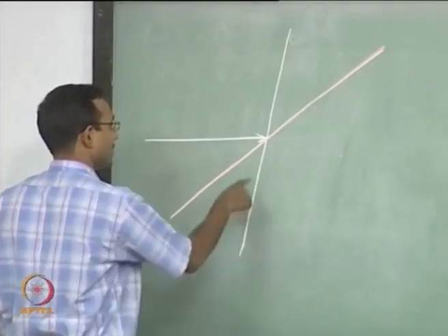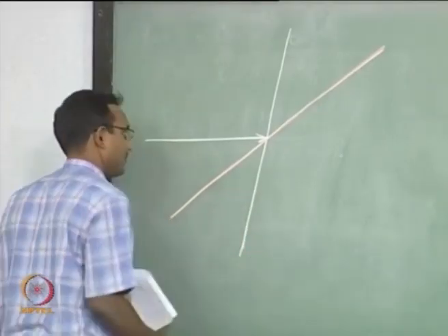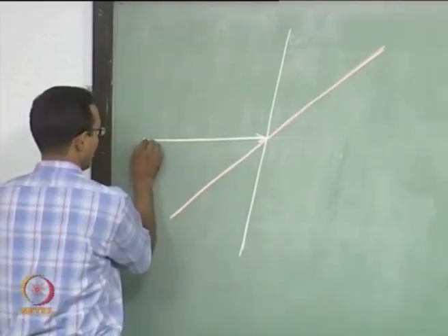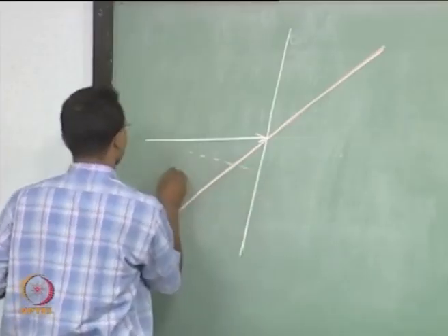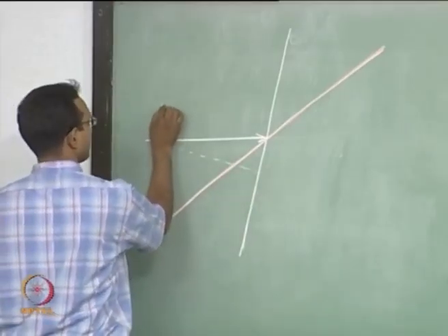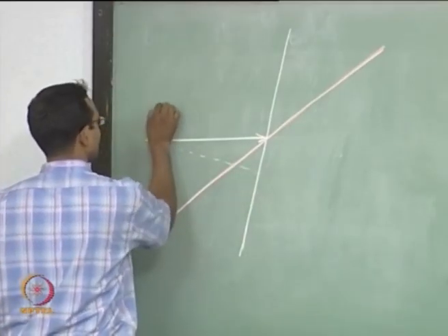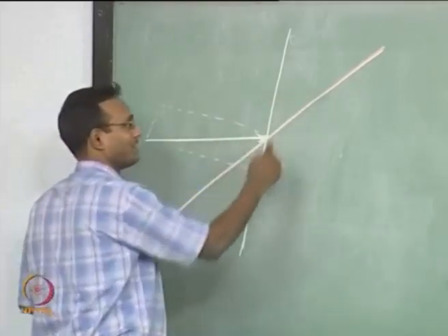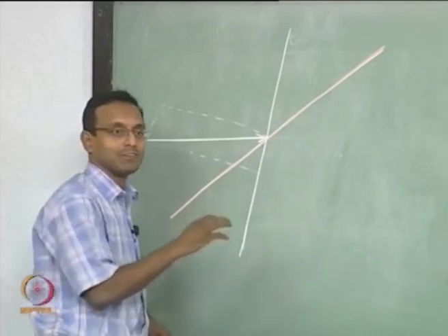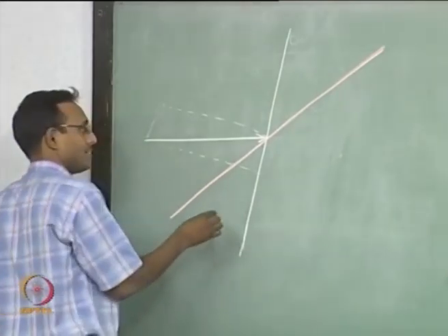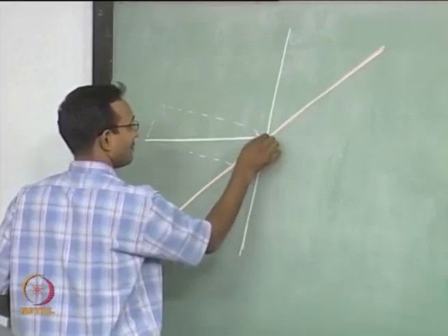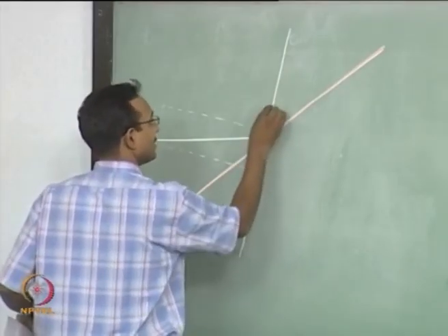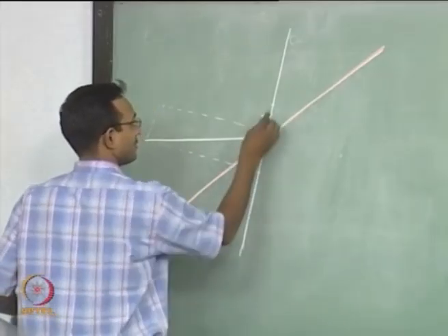So, let us look at only the strong solution first. I have to figure out the normal component. So, I have to drop a normal for this vector. I am drawing in a particular way so that it looks like the downstream velocity vector can be drawn. Now, u tangential should be just translated across that side, so it goes to somewhere here on that shock.